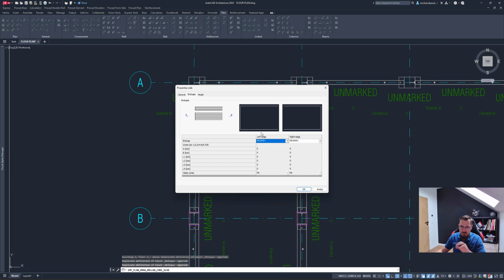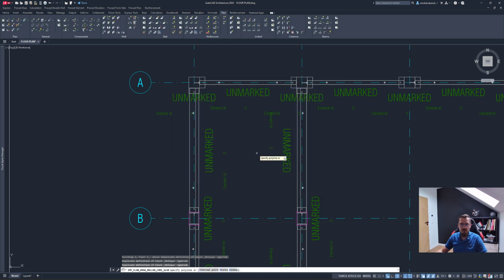End caps, in the end cap section we can go ahead and specify the end caps. By default it's the R1 defined in our standard, or L, which basically is a straight edge. That's it. But for example, let's go with something that we have, HD19U2, as an end cap, which is this nice little rounded cutout. Sorry, let's go and select that too. If you want to add more detail, like a recess or a cutout in the hollow core, then you can of course go by this preview image and add something here of your own choosing. And let us do that now.